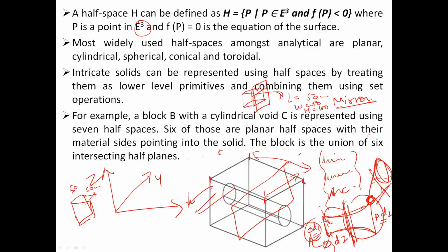Sir, but I was asking, if we take an axis which is along the longitude. No, that is not possible. The concept is the half space. Half space means the whole CAD model is to be broken into two sections at exactly half along the direction of modeling. If this is the direction of modeling that you are taking, this is the plane that you have to select.